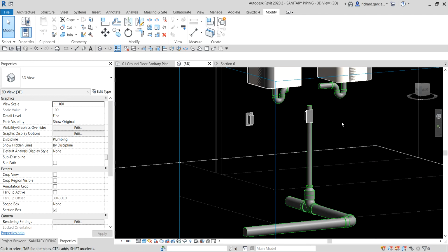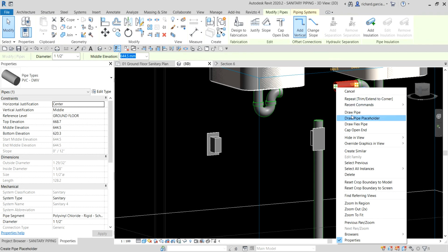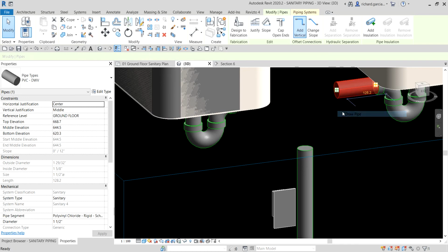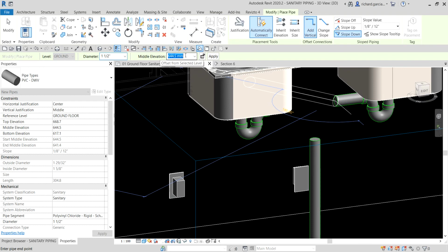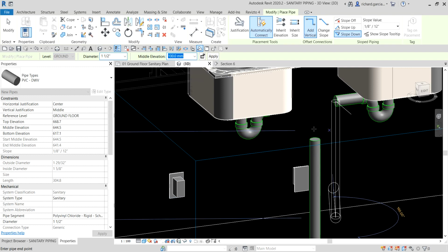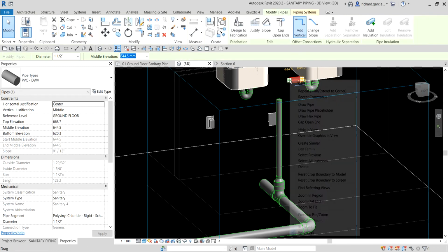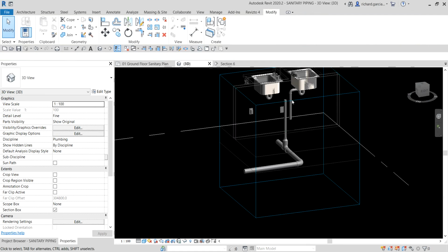Okay, so what I'm gonna do is, how about I'm going to create pipe here. Oops, sorry. Click this. Let's create a pipe. Okay, so what I'm gonna do, I'm going to create a pipe that's going down. So I'm gonna change the offset here. So how about 100 so that it will go down. There you go, and then mod apply. Apply. Okay, oops, doesn't show. Draw pipe. Okay, so 100. There you go. There's the pipe.